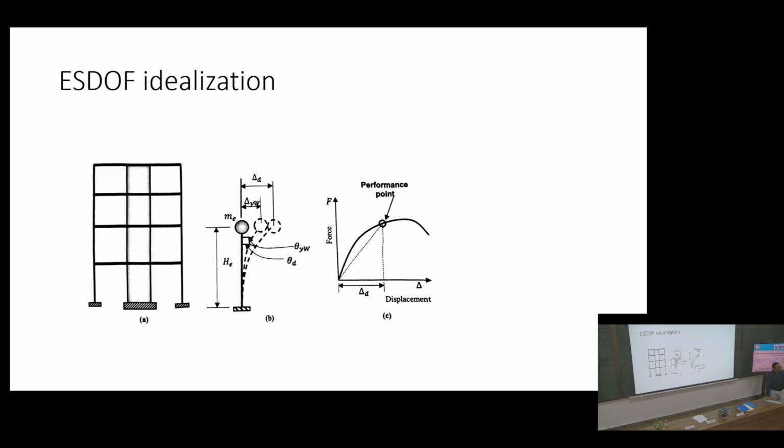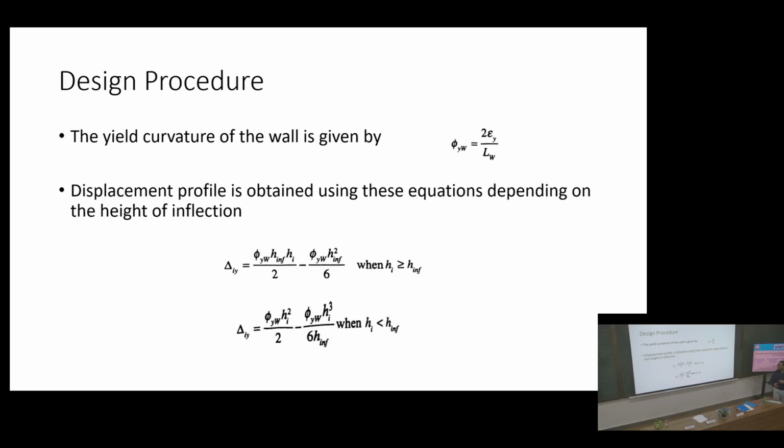Why is the plastic hinge mechanism important? It allows the structure to dissipate energy, right? So we'll get to the plastic hinge in a minute because it's a very important concept, because the wall develops some plastic hinge at the base and we need to calculate the plastic hinge length at some point. For reinforced concrete, it's easy, but for timber, I'll show you an example on Friday. It's still an assumption and there's no research backing this up.